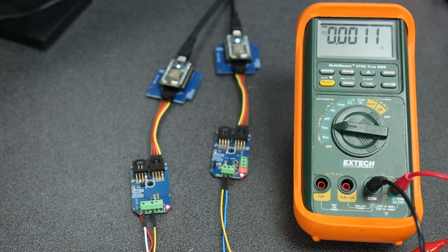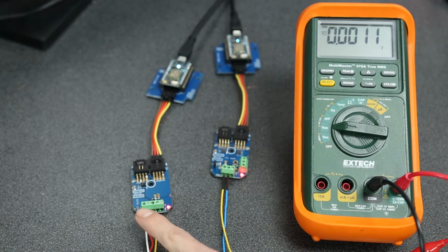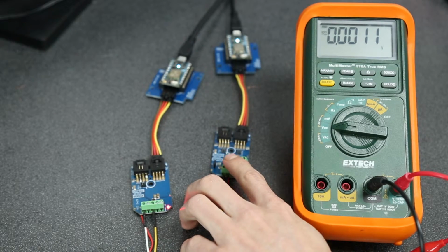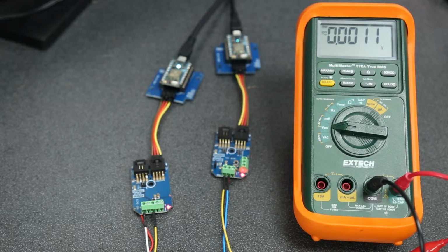And we're doing this all through Particle's Cloud by publishing an event from this ADC board. Whenever the status of this input changes, we're publishing a new event that shows what percentage of the input we're at. So if we turn the potentiometer all the way down, we have a percentage of 0. If we turn it all the way up, we have a percentage of 100. Then that event is published to the Particle Cloud. This device is subscribed to that event. So whenever it sees that new event, it's going to set the output of this DAC based on that percentage. So if it reads 0% on the event, it's going to set it to 0 volts. If it reads 100% on the event, it's going to set it to the maximum output, or somewhere close to 5 volts.